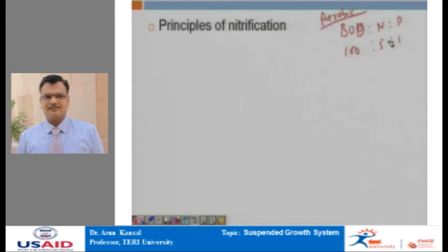So, a part of the total nitrogen coming in the wastewater is removed by the normal activated sludge process in the form of cell synthesis. To give you an example, suppose the sewage has 300 milligrams per liter of BOD and we are reducing it to the discharge standard of, say, 30 milligrams per liter of BOD. That means we have reduced about 300 milligrams of BOD per liter, which we can convert into kilograms per day by multiplying by the discharge.